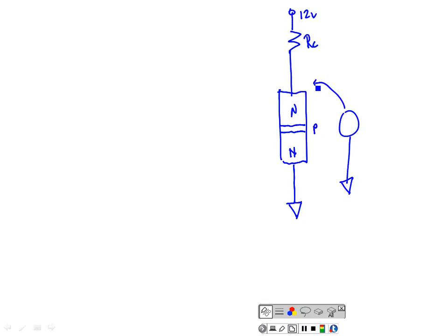Well, any base current. Y'all don't know that? If there's no base current, the transistor is acting like an open switch. So that means I could come up here and substitute for this circuit right here, and there's my transistor. Up here I've got 12 volts. What would I measure across the switch?